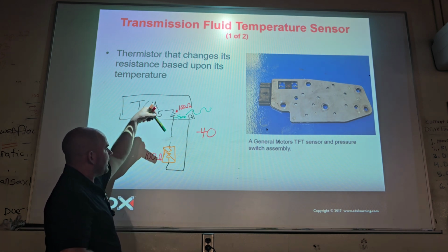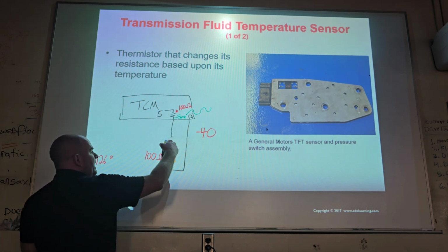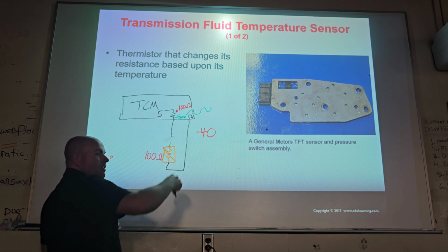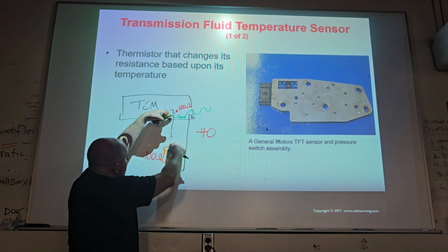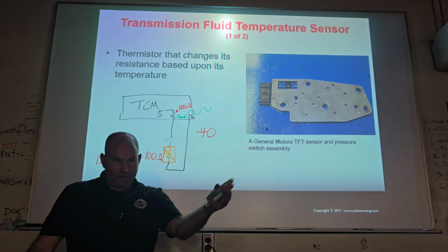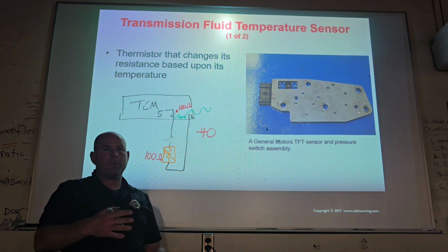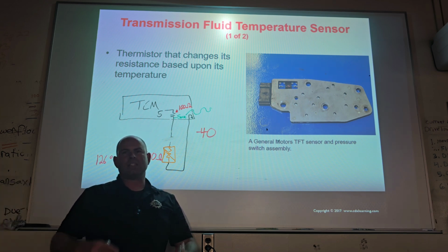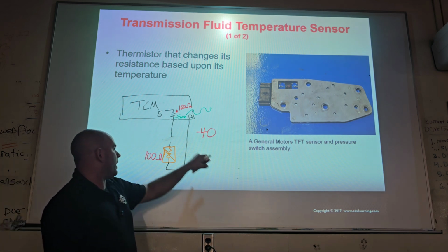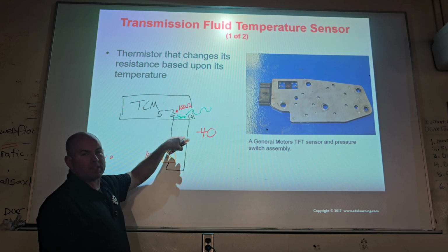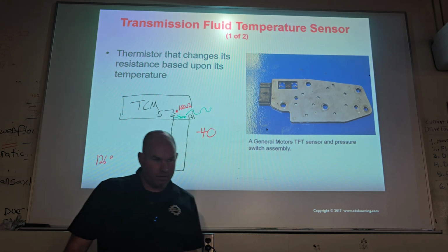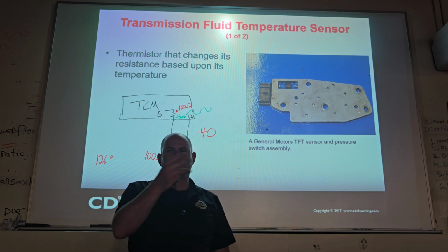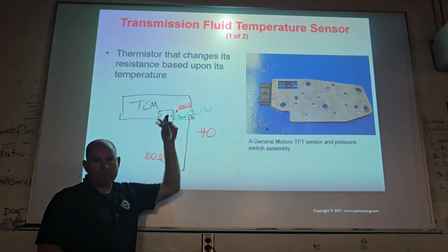Okay. But now that you see, this has infinite resistance right here. You remember in our meter, if you were to measure this right here, what would it read? From here to here. That would measure OL, am I right? OL is like more than millions of ohms. That's a ton of resistance. So now if I'm saying this big brother right there has infinite amounts of ohms, how much is the first little brother going to take right here?